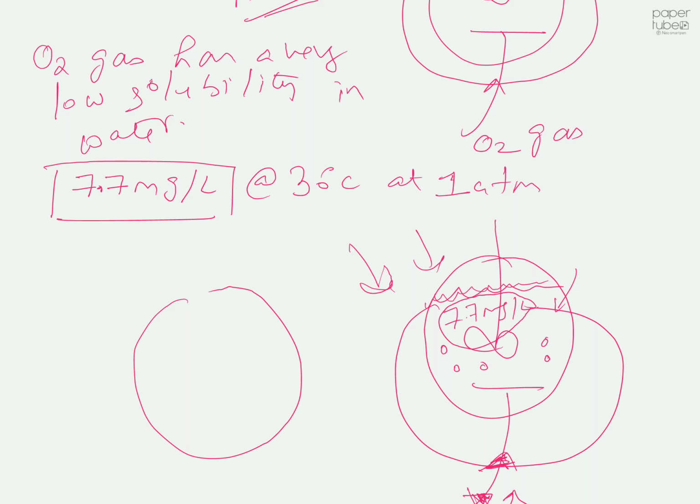But imagine after some time, inside the reactor, the cell concentration is going to replicate and fill the reactor. At this stage, all of these microorganisms are going to breathe oxygen, which means they're going to take all the oxygen dissolved in the solution. So you have to supply more and more oxygen.